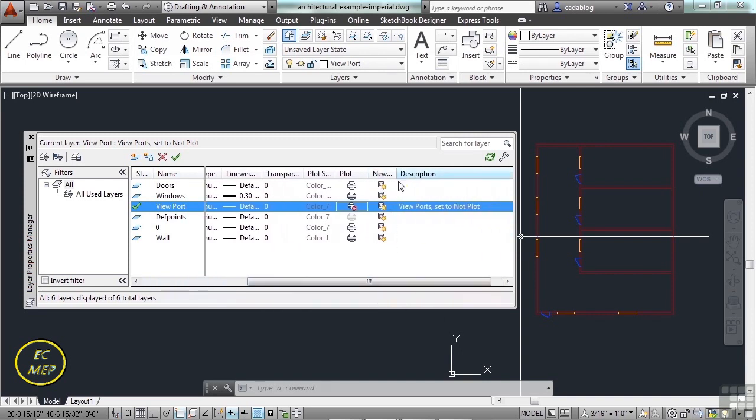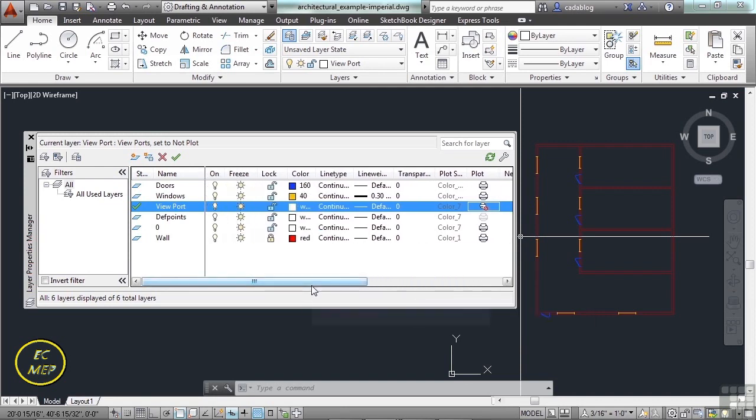This last section here will be a new viewport freeze. That means if you select this, whenever someone creates a new viewport, which we'll talk about in another section, the viewport will have that layer frozen. So if you're working on something specific on a small area of your drawings for the whole project that you don't want other people to necessarily include, this is great for revision work.